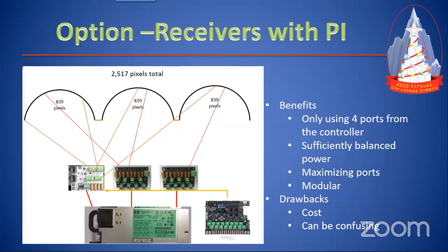The next example is my expertise, which is really power injection. In this case, using just a regular receiver and 4 data ports to control the 2,500 pixels, and then power injecting essentially every couple hundred pixels throughout all 3 of the arches themselves.